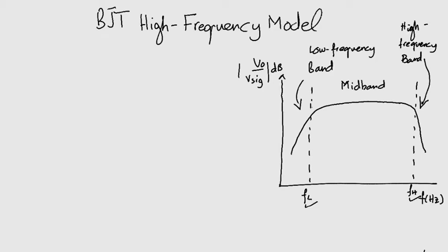The reason behind controlling it is that we want our amplifier to operate in the midband. Here, the gain is almost constant. When we are taking an AC signal, it may have a variety of frequencies. All of them need to be amplified by the same amount, otherwise distortion will occur. So, we design our amplifier in such a way that the concerned frequencies coincide with something called the amplifier's bandwidth. In this way, the amplitudes associated with all these frequencies are going to be amplified equally.